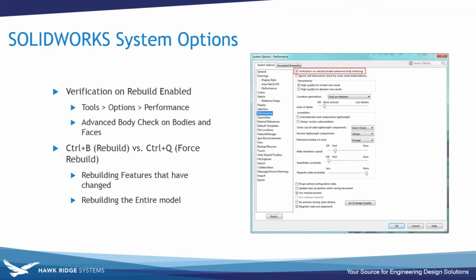And that's why it's a function of this verification on rebuild option that's under the performance. Because if you're rebuilding the entire model or refreshing the entire assembly, of course, it's going to take a lot longer than if you're rebuilding just the components that have undergone some sort of change. But the reason why we want this on is because, going back to my tech support days,